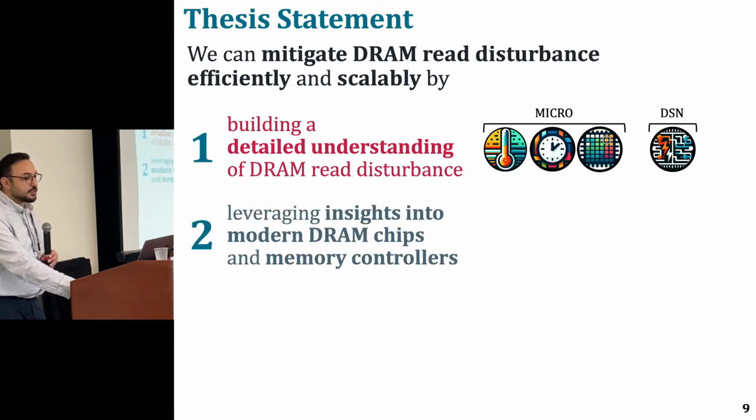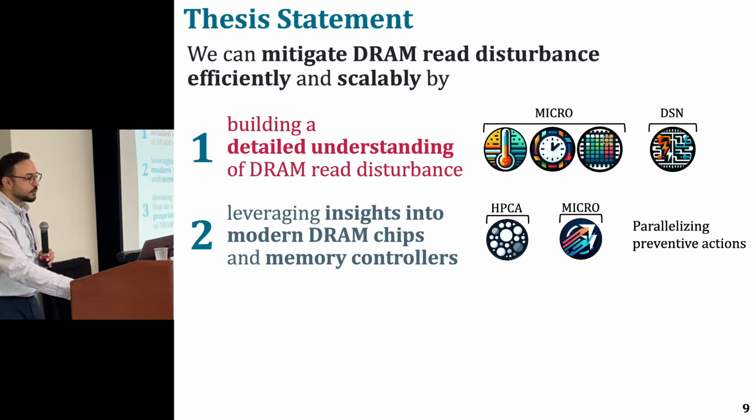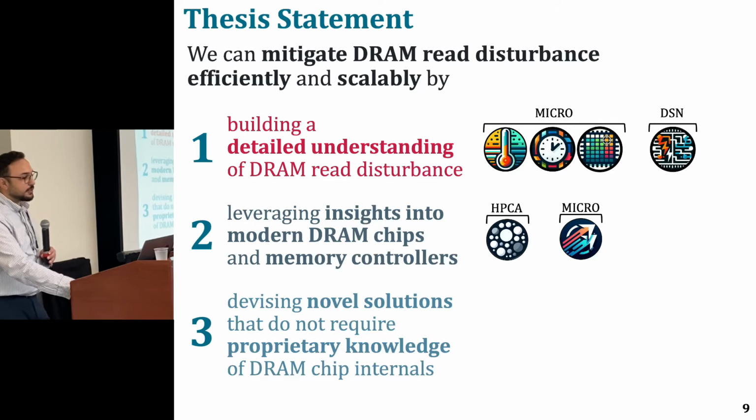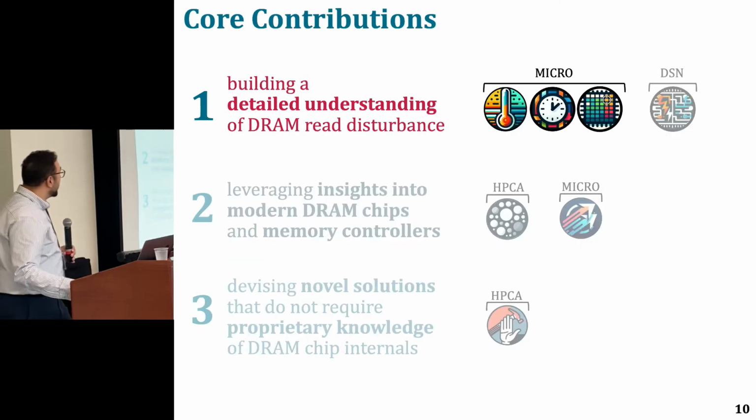Second, by leveraging insights into modern DRAM chips and memory controllers, we conducted some studies and proposed some mechanisms that leverage heterogeneity and parallelize preventive actions to reduce their performance overheads. And third, by devising novel solutions that do not require proprietary knowledge of DRAM chip internals, which we address by proposing another mechanism that selectively throttles unsafe accesses. So this is the list of my core contributions.